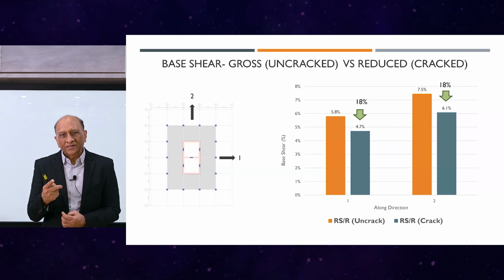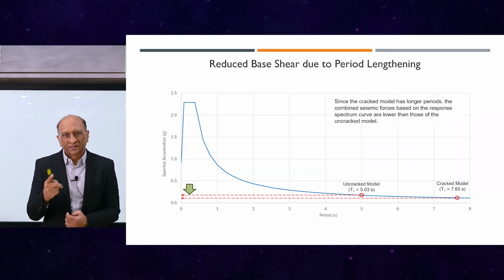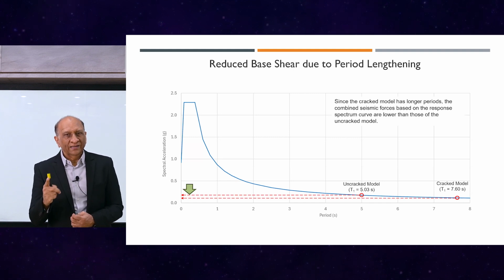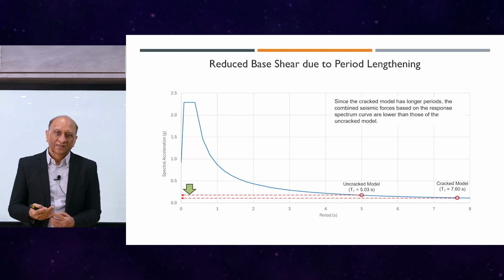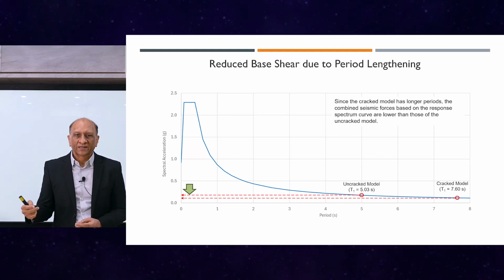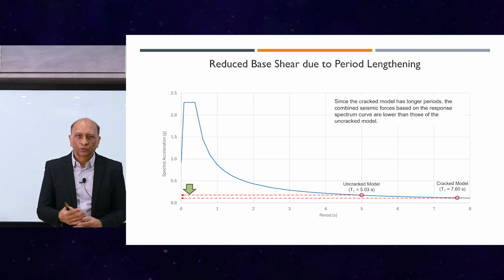So now if you look at the base shear for including and not including omega and R, you can see the difference. If you start with R equal to 1, omega equal to 1, which is the blue, and then include R equal to 6, omega 3 for this structure, you will get very simply a 2 times reduction, or half of the force, because R divided by omega is 2. So the net reduction is only R divided by 3. 6 by 3 is equal to 2. So you get a reduction of 2. It's very simple math, nothing complicated about that.